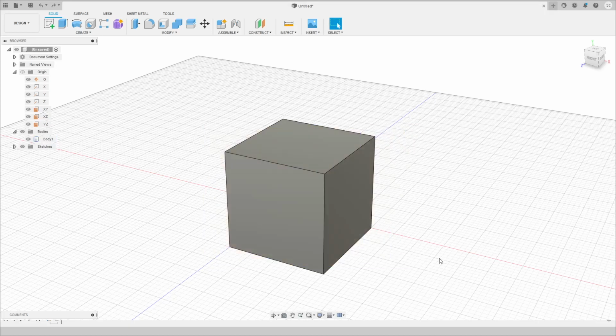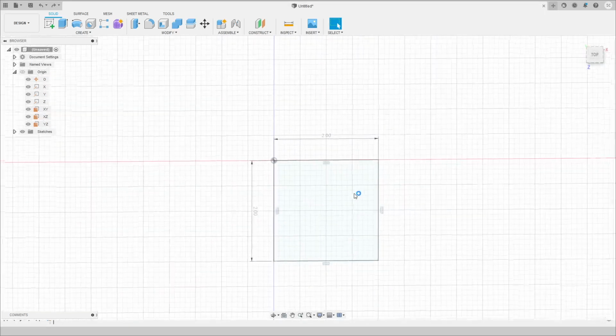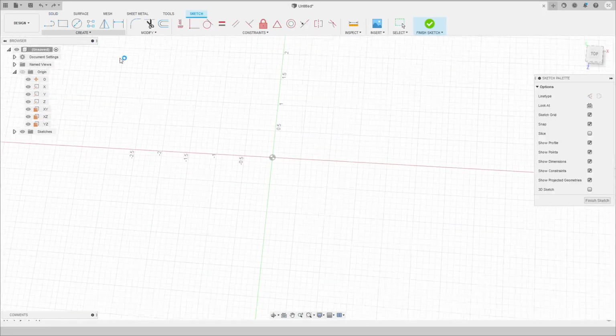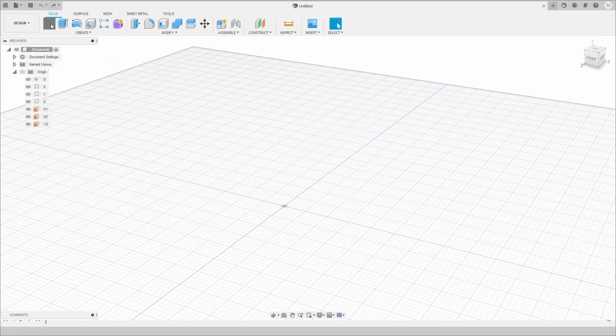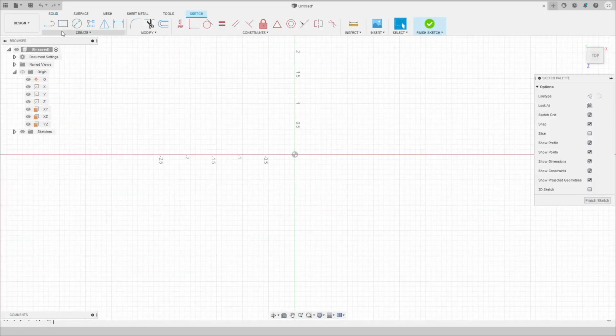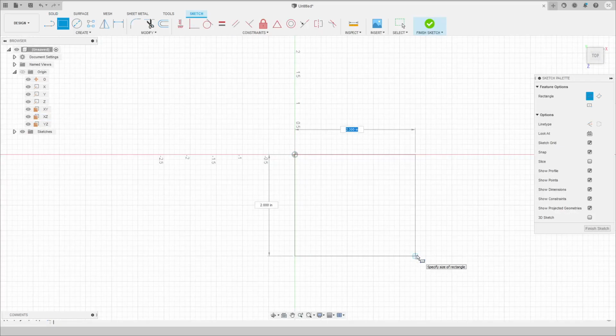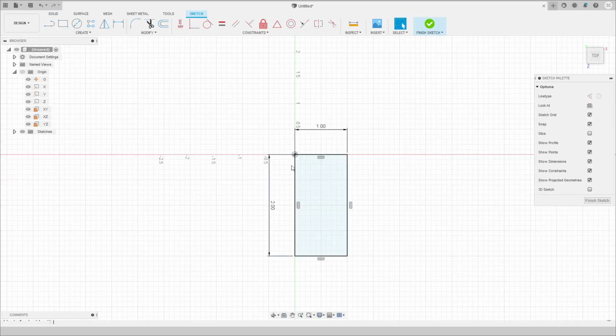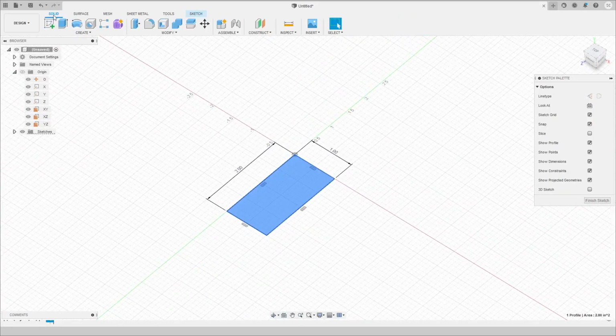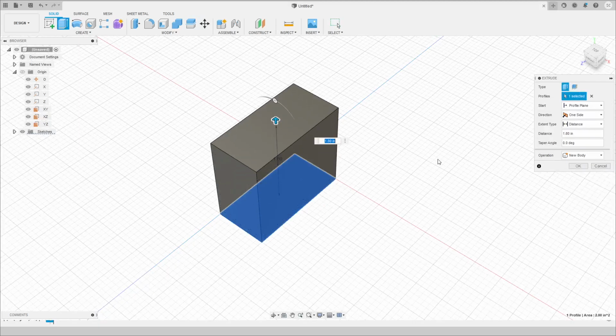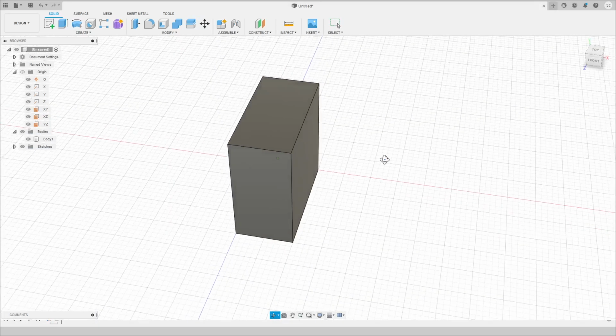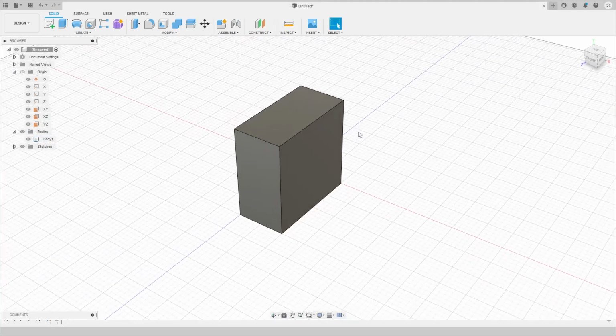But I think we've gone on for long enough. This is how you make a cube, and we'll quickly run through it again. To make a cube, create a sketch on the downwards plane, the floor plane. Create a 2-point rectangle and specify some numbers; they don't have to be 1 and 2. Click on this, click Extrude, drag up, punch in the number you want, and you have your box. That's how you do it.